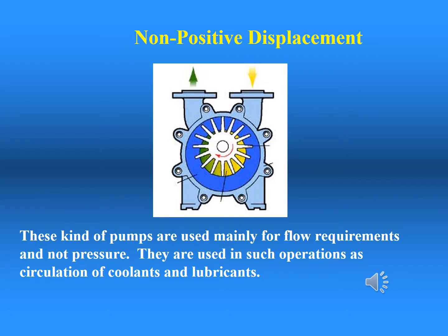There are pump designs which are not positive displacement. These types are called dynamic, meaning they add kinetic energy to the fluid to make it move. The method of flow generation is the same as I have already explained. There is generally a rotary group that begins to move, creating a difference in pressure between one side and the other. While this design would not be suitable for high pressure applications, they do produce large amounts of flow. Examples include distribution for lube oils and coolants, and large volumes for blowers and vacuum units.